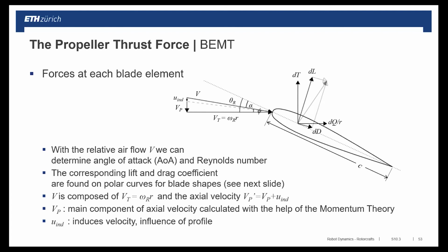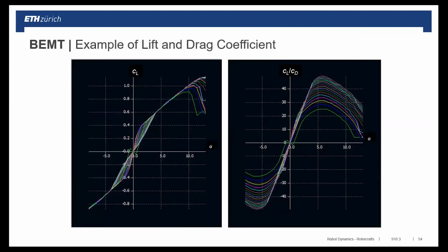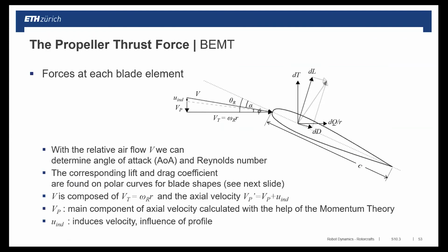Of course, you have to realize that it will vary over the rotor. In the center, you have zero speed in principle, and at the tip of the blades with big helicopters, typically you are close to sound speed. With quadrotors, you are much lower, but you still have a large variation. This is also what you can typically see with some of the quadrotors: they have rotors which are twisted around, because you want a different angle of attack dependent on the velocity as a function of the radius.